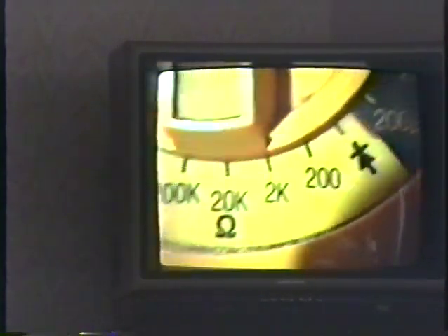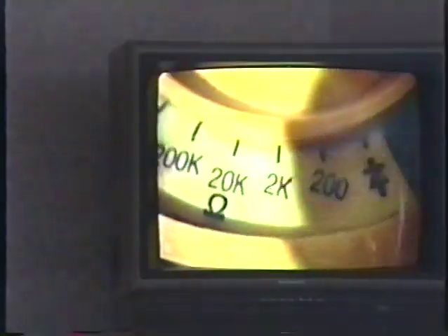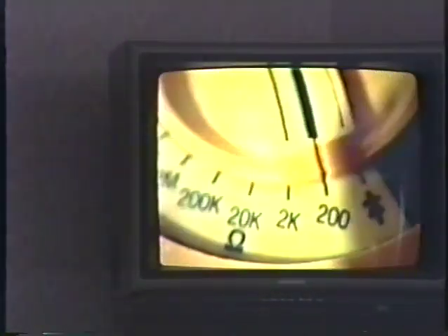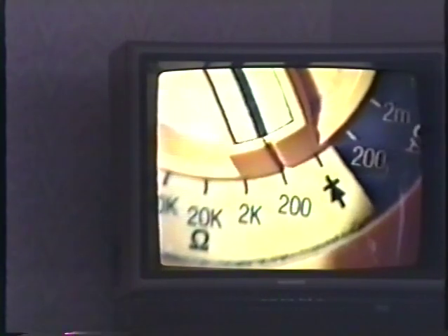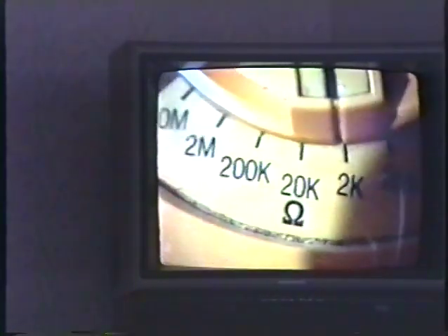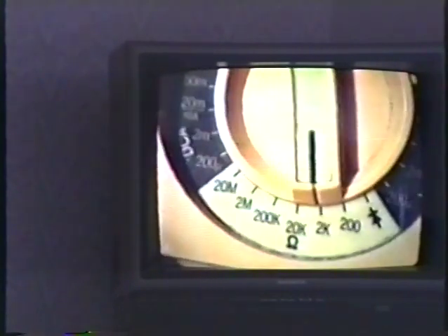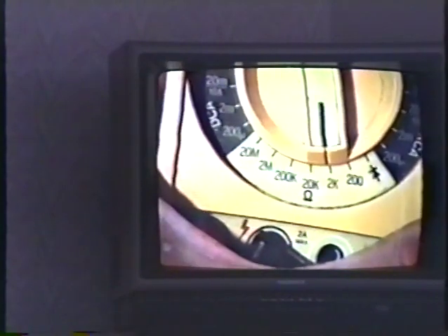If you look at the meter, down here is the ohms department. Right there. For instance, when the meter is set on 200 ohms, we can read up to 200 ohms, actually 199.9 ohms. If you set the meter on the K scale, you can read up to, in this case, 2,000 ohms. Whatever you read on the meter display up here will be in thousands of ohms.